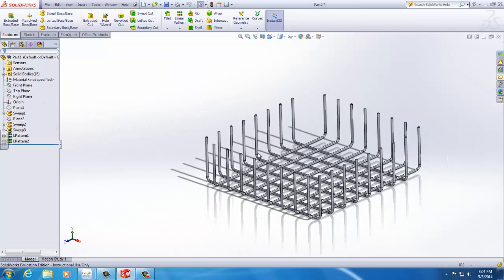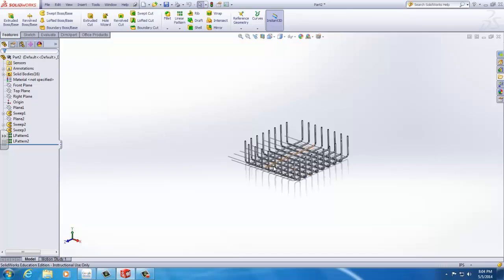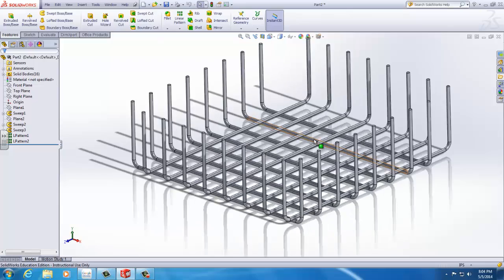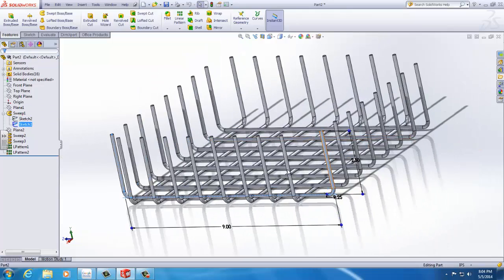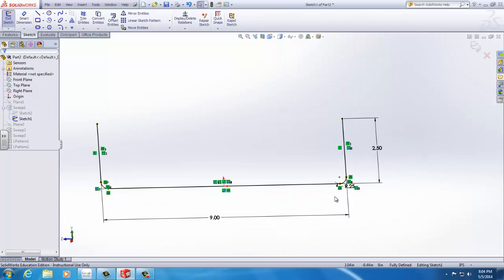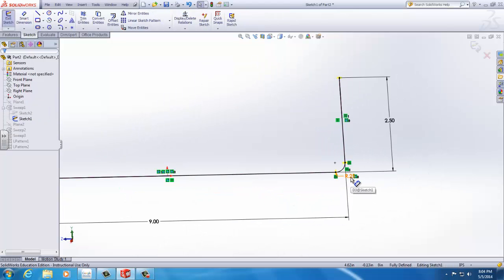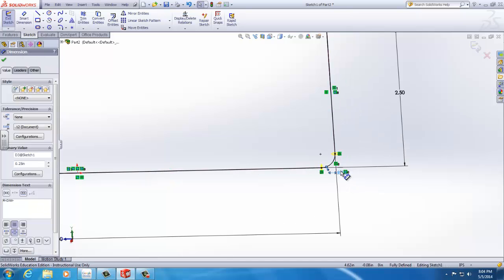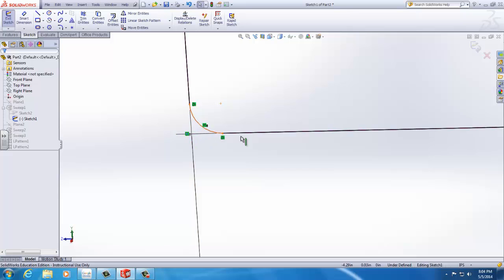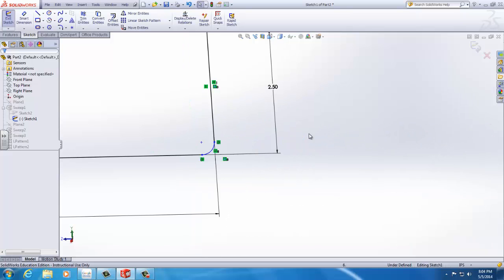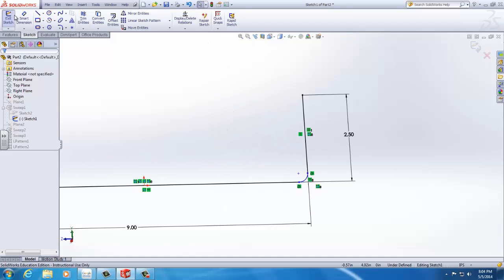To make one flat, to do that, I will add a form. It takes a point here at the origin. We have to actually go back to our original sketch or path. Match these two center lines. And we need to adjust the reference, especially these radii. My second reference will actually be this construction. The problem with the radius is it sets perpendicular. When we make it flat, the radius is going to screw it up. It won't work.